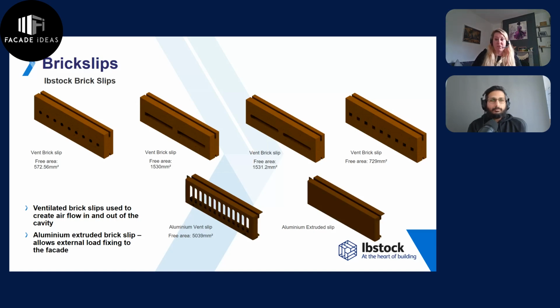These are water jet cut, and they can be matching to the specified brickwork. So they will look exactly the same, but they'll be able to offer that ventilation that's required under our UK building regulations. We also offer an aluminium vent slip, which will offer that full minimum 5,000mm² per metre